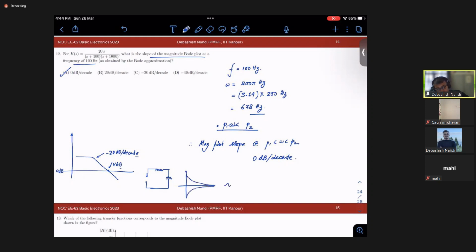It never behaves like a second order system, where you will find some ringing effect, right? It goes there, rings, and then settles. These kinds of things are of second order and higher order circuit nature. This is how a first order circuit behaves. So first order circuits are always stable. Then you would find the phase margins of the first order circuit, then compensate and design your circuit in such a way that it mimics a first order circuit. This is one way to put it.